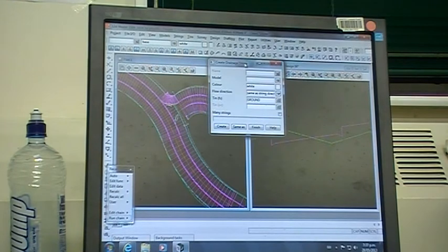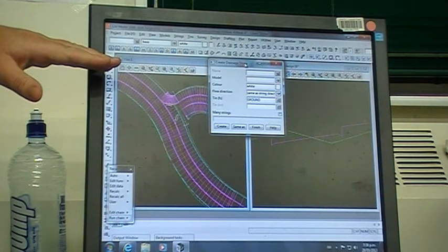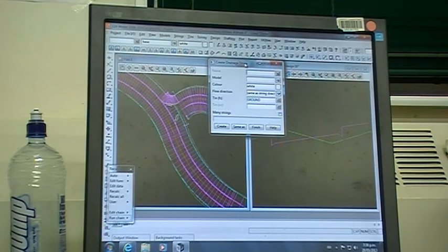The naming convention I use will depend. It differs from office to office, but it tends to be standard. The more common is that I call my stormwater lines line A, B, C, D, and my wastewater lines 1, 2, 3, 4. It doesn't matter which, but pick one or the other, so that you don't end up with two manholes, A1, B2, just to save confusion. Go for letters for one and numbers for the other.